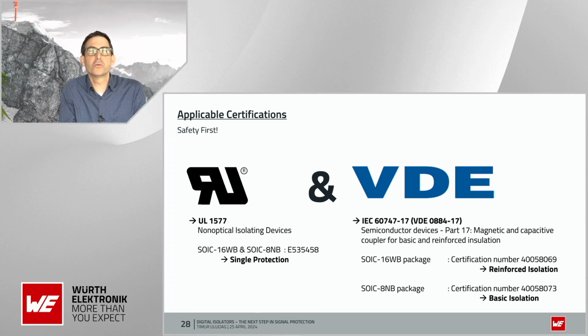For those who do not know the IEC 60747-17, let me explain a little bit of the philosophy. The philosophy of the standard is to test the reliability of the insulation over time with a destructive end-of-life test program. So there are a lot of parts in the qualification phase that are tested really, really hard.